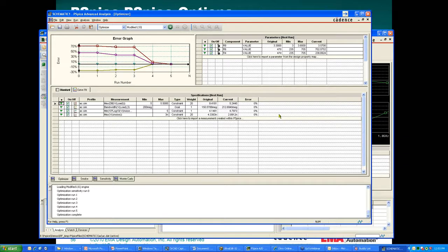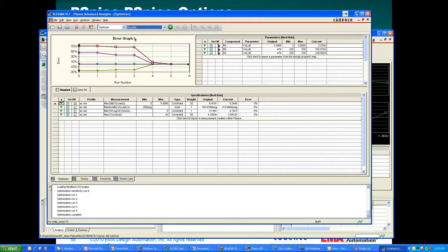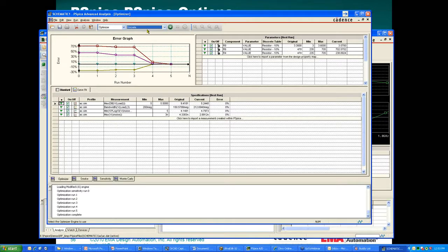Now the next thing to do is, okay, these components, I can't really buy those very easily off the shelf. So I wanted to run one more time and get a discrete value associated with those components, so I can go buy off-the-shelf components for this particular characteristic. So I set this up to run one more time using discrete component values, and it'll do one more run, give me an adjustment on these values, and tell me what kind of standard values I can go get for these.